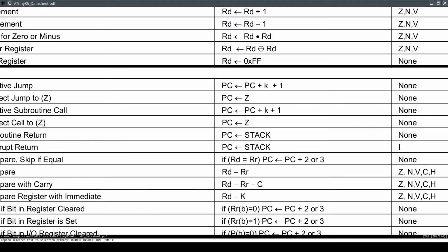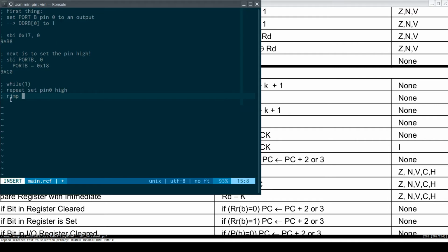Now be careful. Remember this plus 1 here? Usually the next instruction, this one, program counter plus 1 is this. When we do our rjump, we're going to go here, that's our next one, but we want to go back. So when we're on our rjump, our next one, program counter is at this location instead of here. So we need to go back by 2.